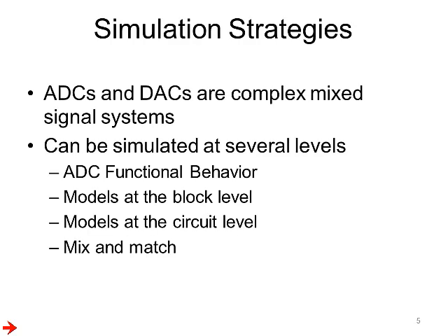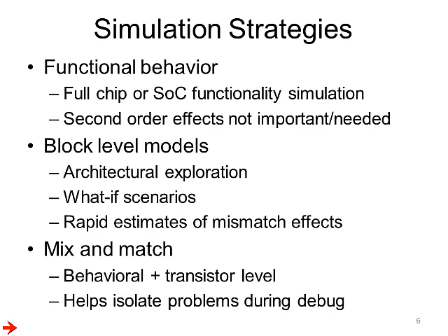ADCs and DACs are complex mixed signal systems and can therefore be simulated at several levels: at the functional level, at the block level, the circuit level, or a mix and match of these approaches. A functional behavior simulation is often important in full chip or SoC functionality verification. Second order effects are not important or perhaps not needed in such simulations.